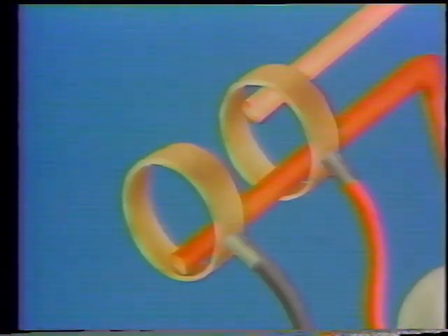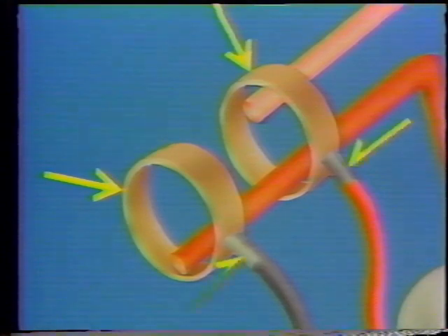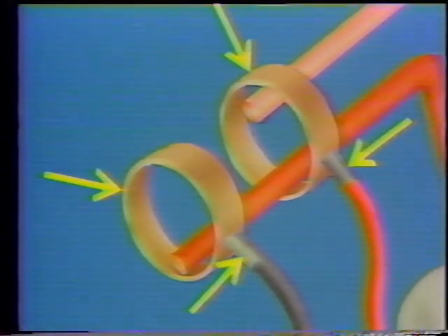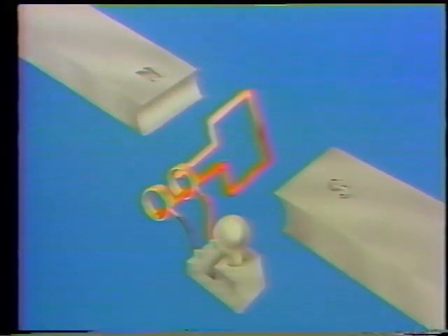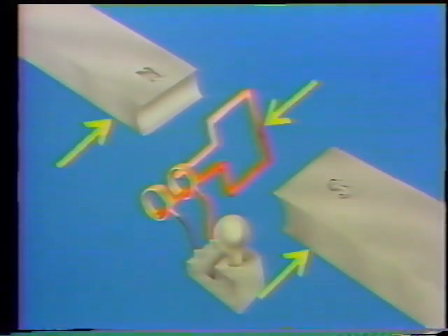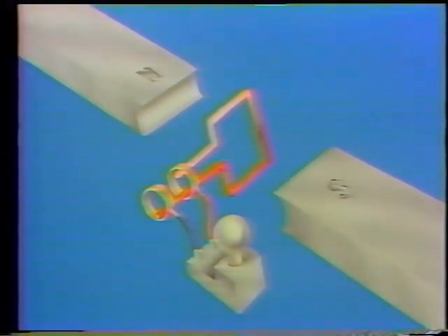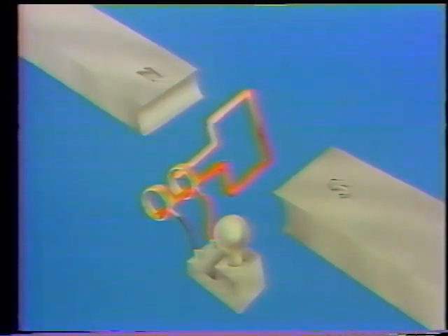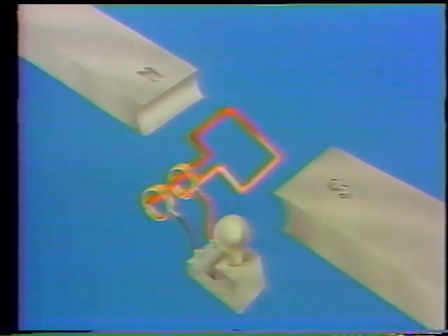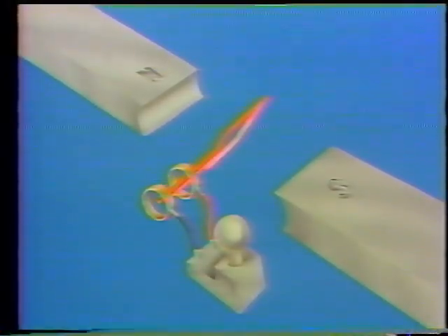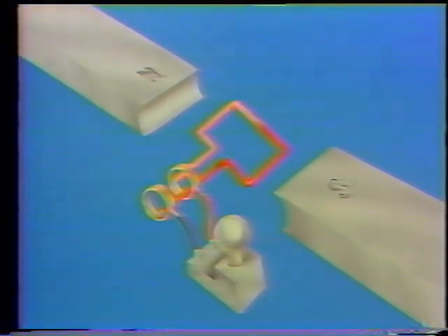In our generator, the slip rings are made of metal. The brushes are made of carbon, a material that can maintain good sliding contact with the rings. This is our AC power source for the moment. We'll be using magnetism to induce voltage. We have a magnet and a conductor. We need relative motion. To induce voltage, we can do one of two things. We can move the magnet in our generator through the loop of wire, or we can move the loop of wire between the poles of the magnet. The point is that either the magnet or the loop of wire must be moved.